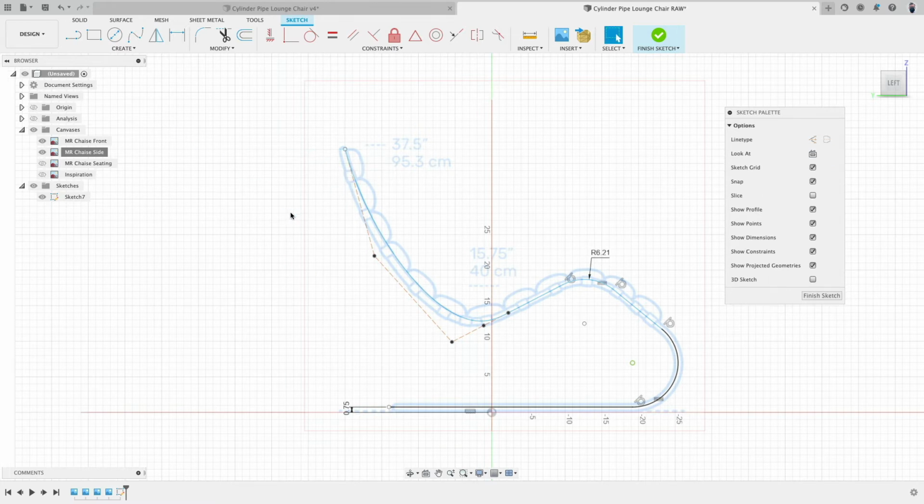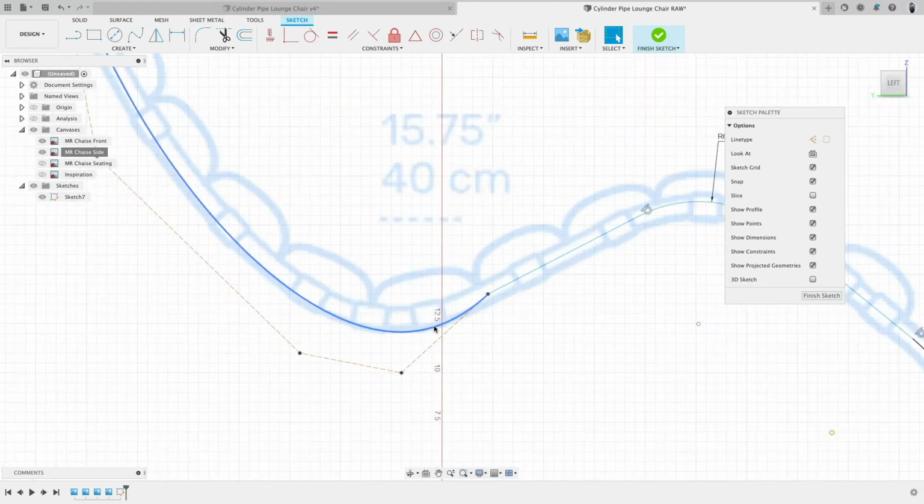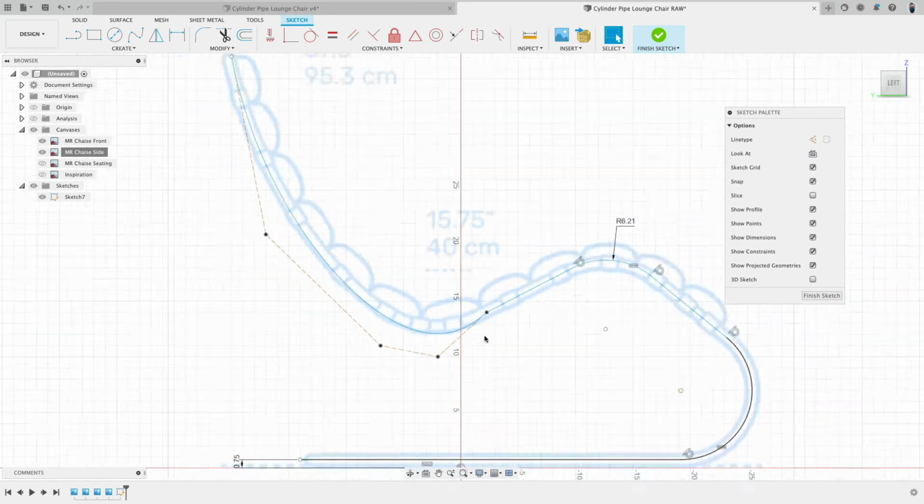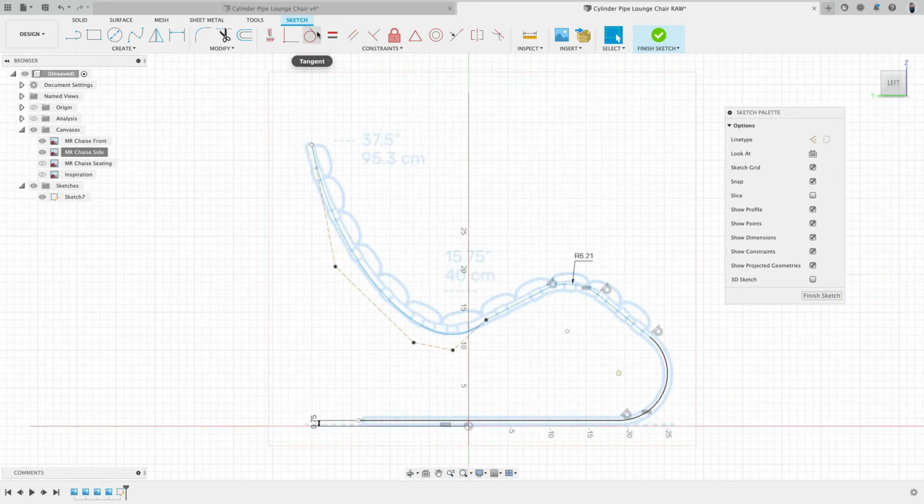Okay, and escape, so I don't do anything anymore. Then I can click and drag everything. Here is now the interesting process to do. I moved this point down a little bit on purpose. When we zoom in here, you can see how this curve to this line is not very smooth. I want to create a nice smooth transition.